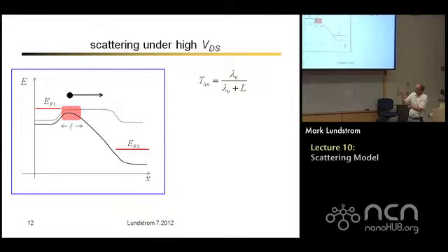There is this short region under the control of the gate where the electric field is low. The electrons are injected with near equilibrium thermal energy. They have a mean free path that's close to the one you would deduce from the mobility. And if they backscatter there, it's easy for them to return to the source. So the scattering in that little region, which is just a small fraction of the channel length, is a bottleneck. That's where the scattering matters.